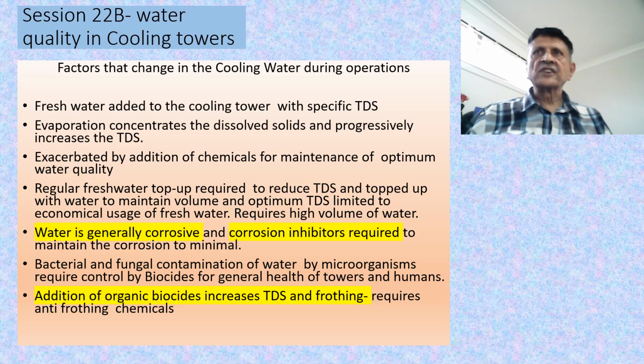The factors that change in the cooling water during operations: when you start with a new tower, fresh water is normally added to the cooling tower, and it has some specific total dissolved solids. In some areas, the water may be of very good quality and very low TDS, as low as 20 ppm, and such water is very good as a starting point.